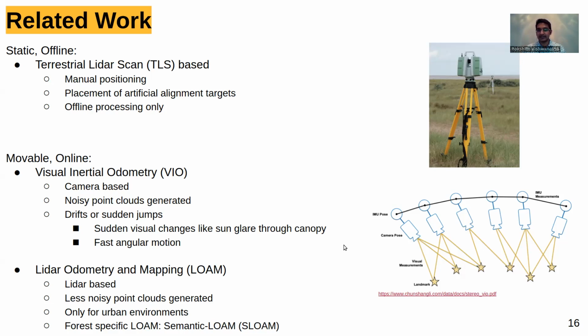And I saw this while I was collecting data as well. When I had only VIO data at one particular location while collecting data from the Palo Verde, sensor values would jump by about 15-20 meters, and then it would start localizing around that new 15-20 meter offset location. So those kinds of problems can be avoided. And ideally, merging both LiDAR-based odometry and VIO, which is what GTSAM does in this case, would be a good approach, is what I think.